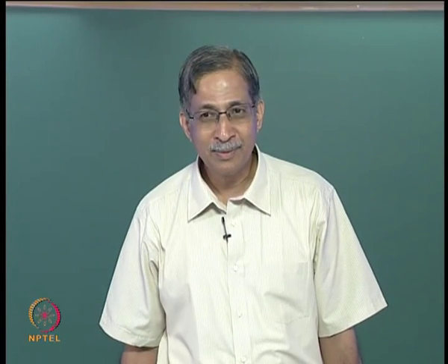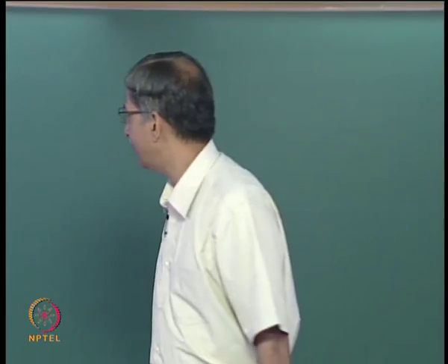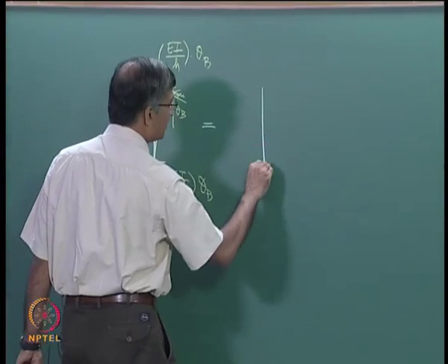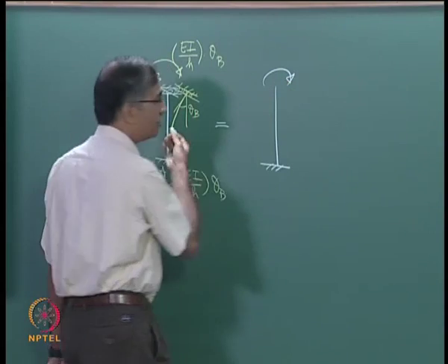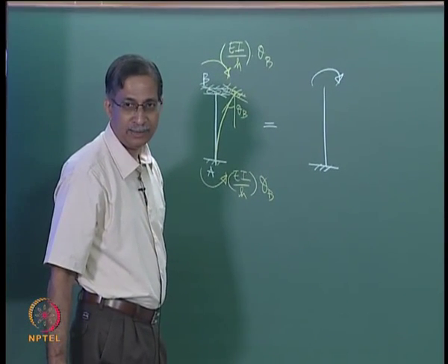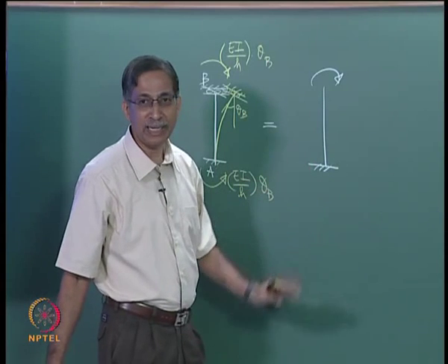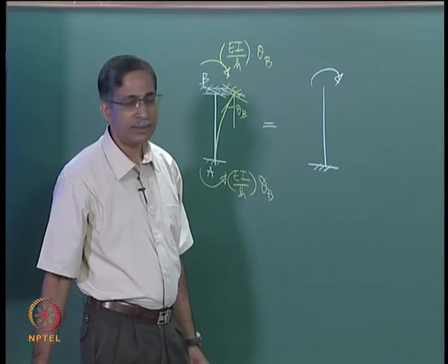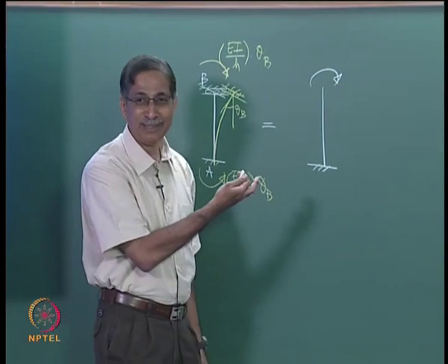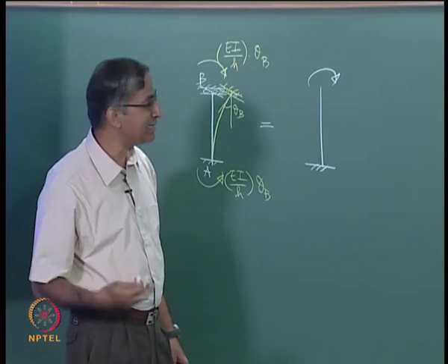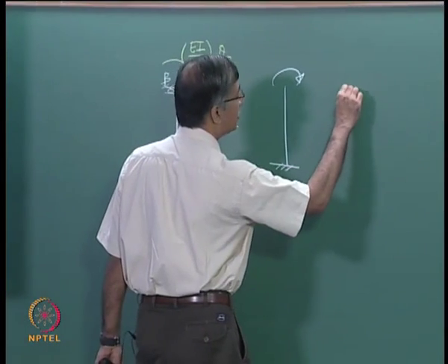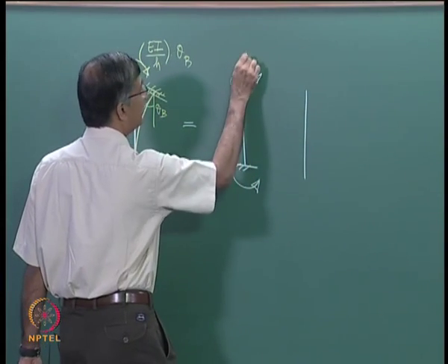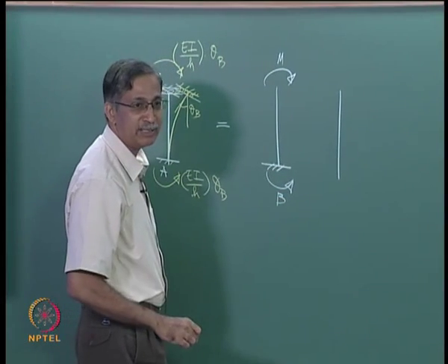Speak louder. Why is the moment clockwise at B? This is the same as this, by the way. There is no difference. Okay. Which way do you think this is going to sway? Left to the left or to the right? Okay, let us say this is a common problem of intuitive understanding many students have. What is a bending moment diagram? Let us look at this. You will get the same moment here, right? What is a bending moment diagram going to look like? Drawn on the tension side.